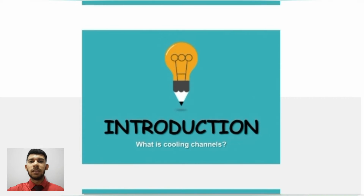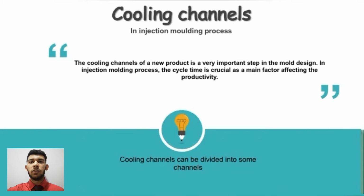Okay, so what is a cooling channel? Based on the first point, this productivity can be improved by determining the dies or mold with conformal cooling channels. The technology that is used in this process is additive manufacturing technology, such as selective laser melting. The laser technology allows the manufacture of complex conformal cooling channels in the molds or dies. There are a few types of cooling channels, which are conventional cooling channels, parallel conformal channels, and series conformal channels.